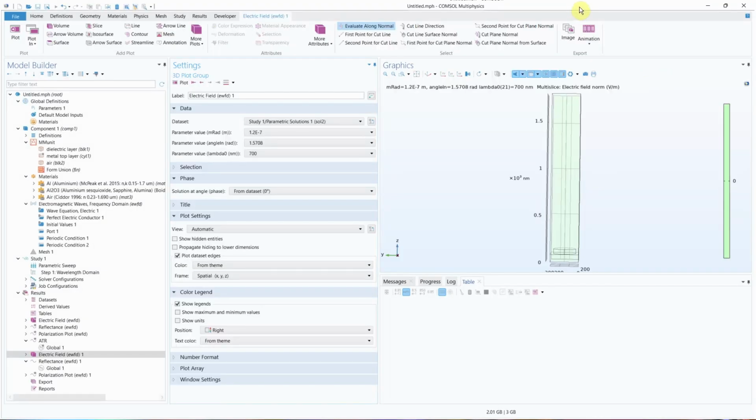Now that my simulation is finished, we've opened up to the screen that you see here. You'll notice everything is a 0, which initially makes you go, oh no, it didn't work. But remember that for our angle of incidence, we did a sweep, right? We did 0 degrees, 45 degrees, and 90 degrees. Here it says in radians, we have 1.57 radians, which is in fact 90 degrees. And so this is where the input wave is parallel to the surface. So it's not actually even interacting with our material, based on the orientation of everything. So it makes sense that nothing interesting is happening in this condition.